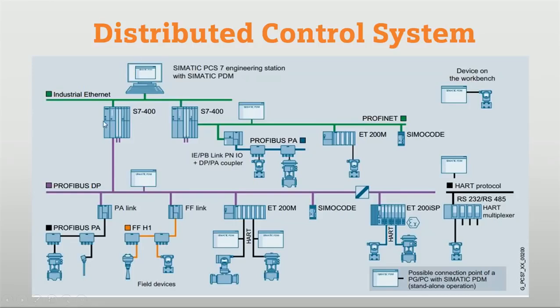This automation station is the master control or dedicated control, and from this automation station we have connected this coupler with Profibus DP, and from the coupler we have connected these field devices with an active field splitter or active field distributor. Those are networking devices that we'll see in the next slide.